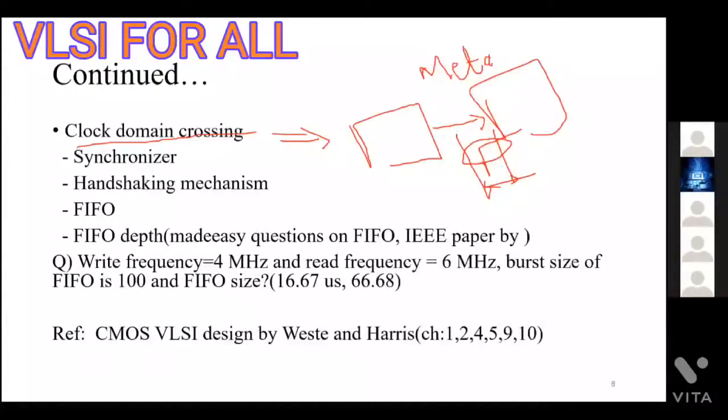Now, this should be avoided. This can be avoided using the synchronizers. Synchronizer is a two flip-flop design. It can be of any number of flip-flops even, but generally they will prefer these two flip-flops.